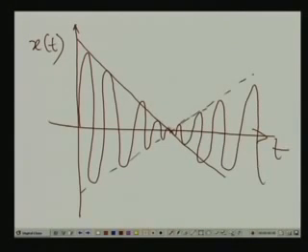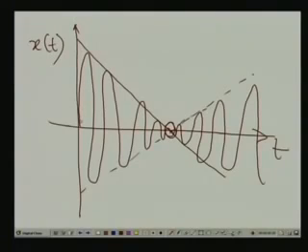Now the thing is that this phase change occurs at nearly 0 magnitude, therefore it can't be seen. What you are going to see, if you connect a cathode ray oscilloscope (CRO) to the LVDT terminal, is this. So, obviously you can't make out whether X is positive or negative.